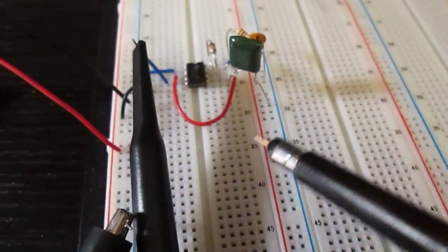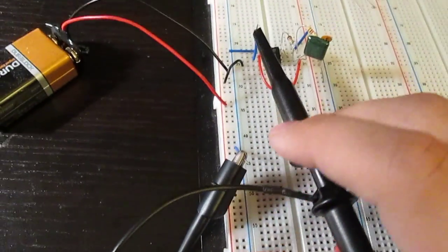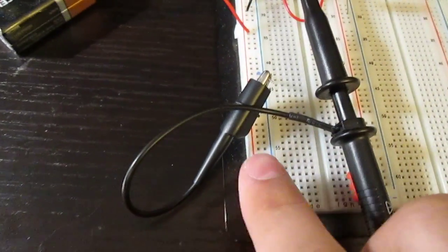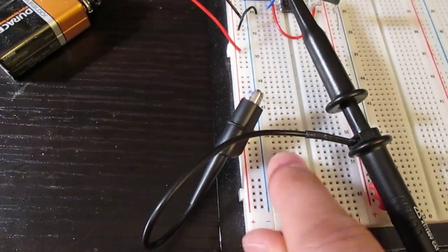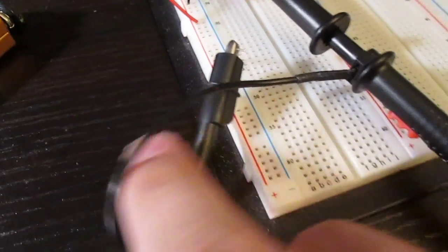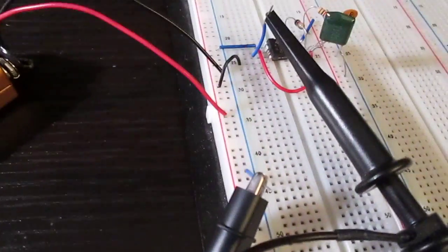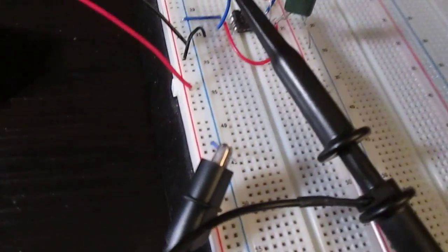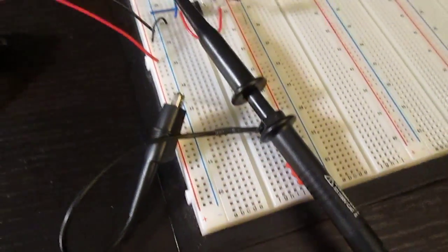That way you get a nice solid ground. And that's really important when you're measuring high-speed signals, is to get a really nice ground. Something like this would never fly. The reason being is because you have a lot of switching occurring, and that EMI, that electromagnetic interference, will come up from the board if it's powered on, and it's going to affect this ground, and then it's going to go into your oscilloscope and affect the ground plane on your oscilloscope, and then you'll be getting false readings. So you want to make sure that you're always using the smallest ground possible. In a use case like this, it doesn't matter, especially since I have nothing switching over here. It's not a big deal.